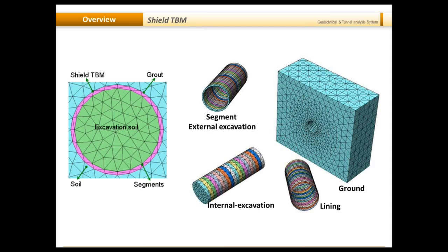These can be the precast segments of concrete, and there is tunnel lining also. Before the segments are installed, there is lining, and then this lining is replaced, and then we have the segments installed, and between the segments and the actual ground there will be grouting. So this lining would then be replaced with the grouting material.